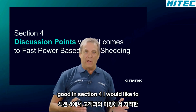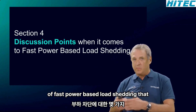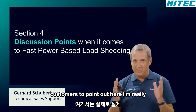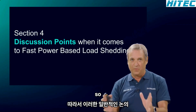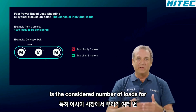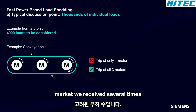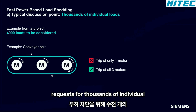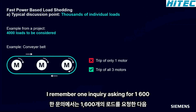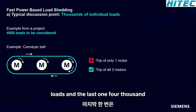Good. In section 4, I would like to present some typical discussion points of fast power-based load shedding that we have noticed in our meetings with customers. To point out, here I'm really talking about real life. One of these typical discussion points is the considered number of loads for load shedding. Especially on the Asian market, we received several requests for thousands of individual loads to be considered for load shedding. I remember one inquiry asking for 1,600 loads, then came one with 2,000 loads, and the last one, 4,000 loads.